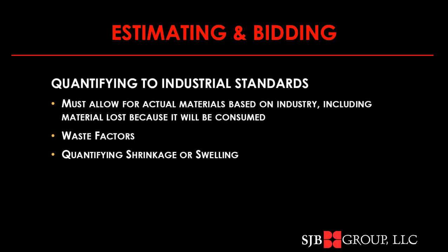And you have to quantify for shrinking or swelling of the work. A classic example is earthwork. It's in the ground at one size. If you dig it out of the ground, it swells much larger. And then when you go to use it in a hole, it compacts in place smaller than the hole it originally came out of. So you have to track and price the volume of, it's the same dirt, but it's different volumes at different parts of the process. And you have to use the appropriate quantity for the pricing of each part of that process.